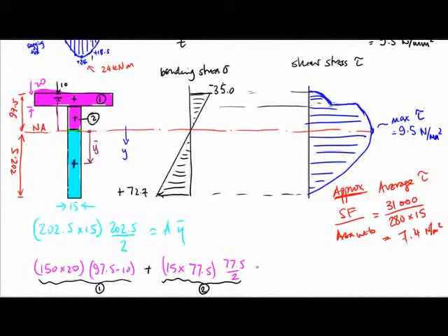And what I'm saying is, when you add both of these up, you get the Ay-bar for the pink block, and in both of these, if you calculate it, both actually equal 307,550 millimeters cubed. So the point I'm making is, when you've made the cut, it doesn't matter whether you look at the area above or below, you get the same Ay-bar.